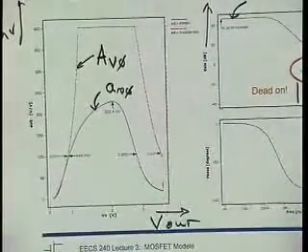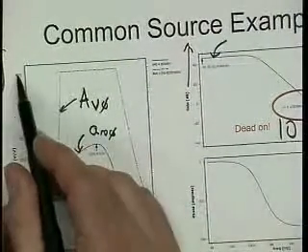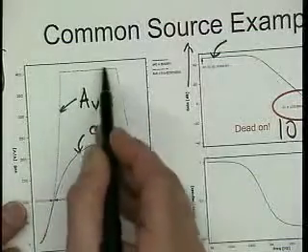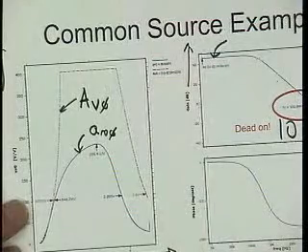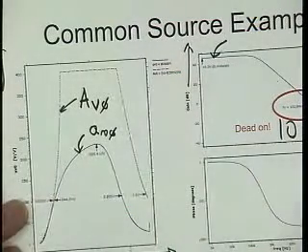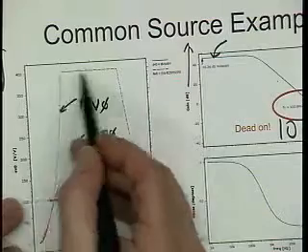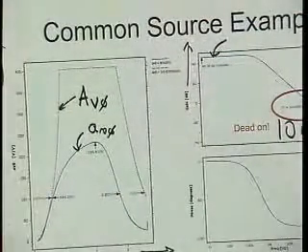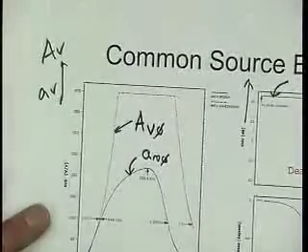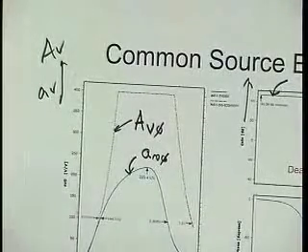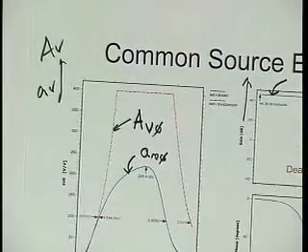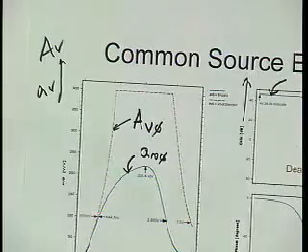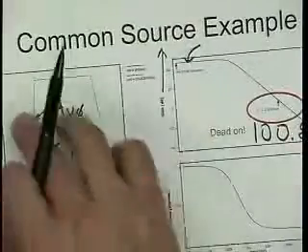So again, how much gain do we get? Well, actually this thing goes up to more than 400. The reason that we have this flat top here, of course, is not that the amplifier has such a bizarre gain characteristic, right? I've warned you that stuff like that doesn't happen in physics. It's simply because I clipped it, because it probably would have gone up. Actually it very often goes up to infinity, simply because we divide by Vin, and Vin at one point is 0, and then if the amplifier is a little offset at the output, 1 microvolt divided by 0 is still infinity. So this goes up too.